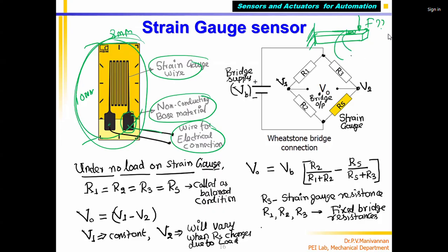Okay. Now you apply a force, what will happen? The cantilever is going to bend due to the force. So slightly it may bend like this. Correct? It bends. So what will happen? On the top side, it is expansion, correct? Top surface is expansion. Bottom surface is compression. So that means this length reduces, L minus delta L. This is L plus delta L.